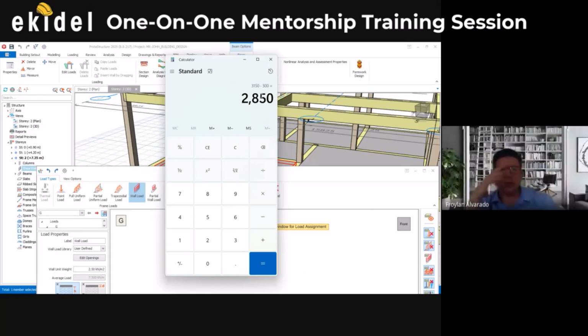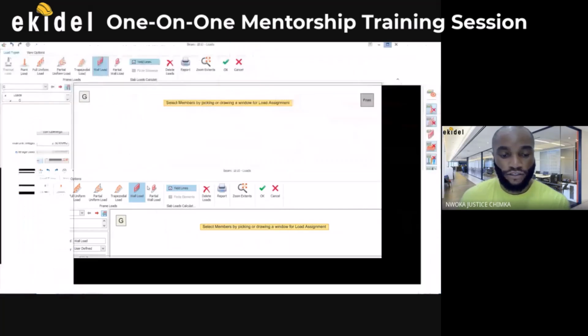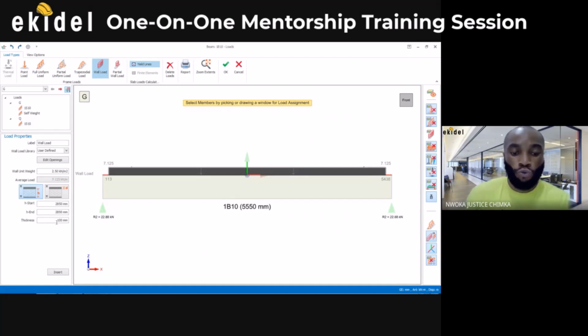Yes. So you're taking the total height minus the beam height, and that gives you the block height. Exactly. So with this, we now put this value. This is 2850. So come and put it here under the height, 2850. That's fine.